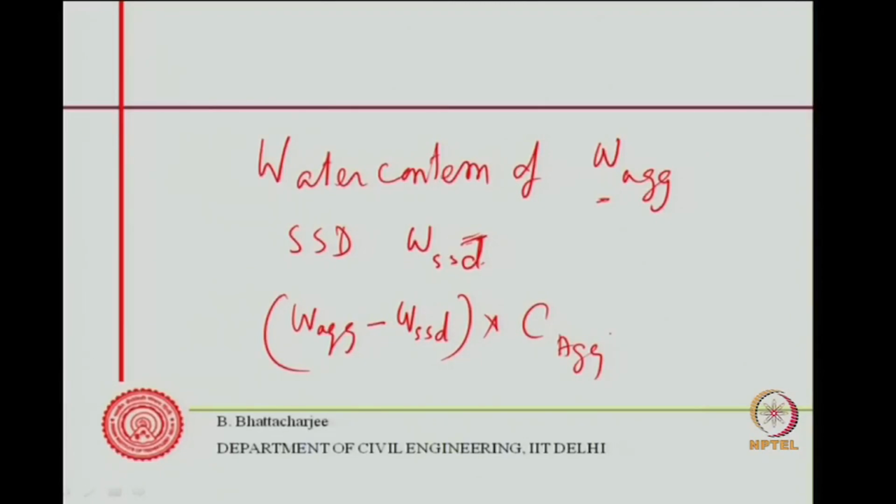This quantity of water is additional water, this must be added, and correspondingly you must add aggregate as well, because aggregate contains additional moisture. If it is less moisture, then slightly more water should be added, because a good lot of it will be absorbed to bring it to the SSD condition, and the aggregate quantity that you are adding should be less than the actual measured aggregate quantity, because in SSD condition mass will be higher.